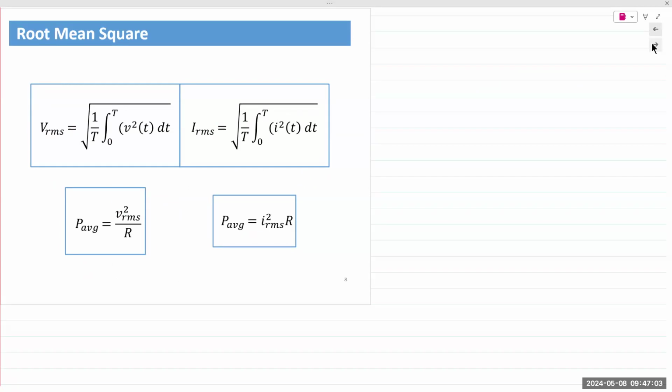Okay, so that's more popularly known by its acronym, RMS. But RMS stands for root mean square. It literally is the square root of the mean of the square of the waveform. So here you see it. We have v of t, the function. Mathematically, we square that function, then we take the average.